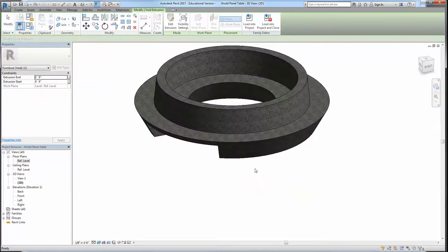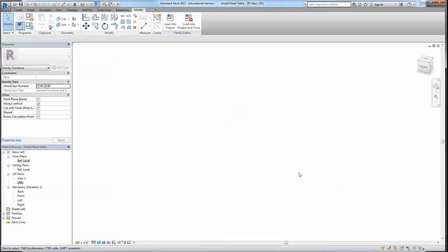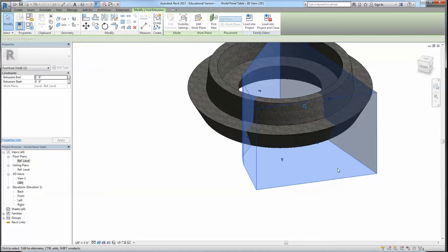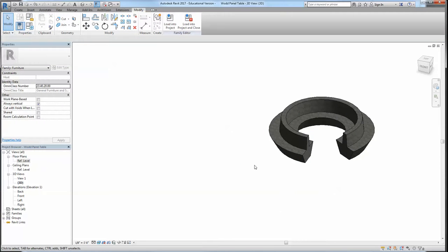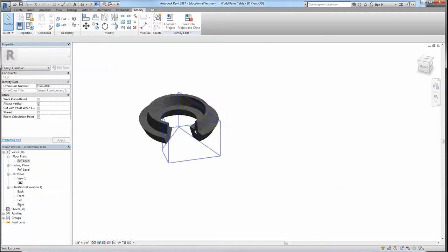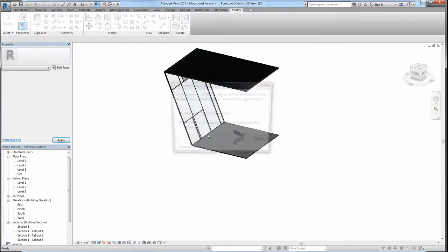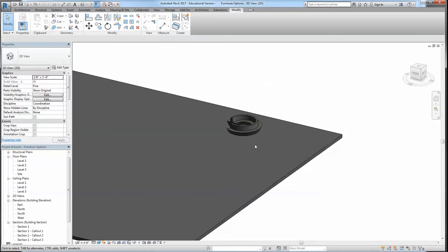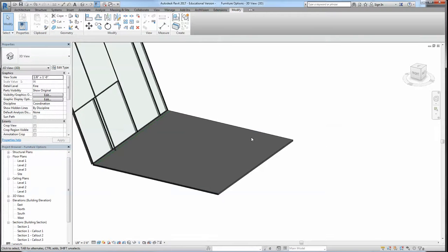Go to the 3D. Again, that's an extrusion void. We need to select the void and drag it up so it cuts the whole thing. Okay, so that will be loaded into the project, override, and there is a little thing to be utilized as a bench.